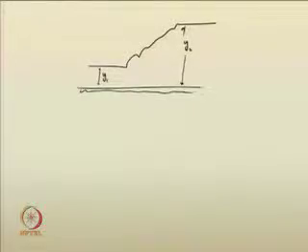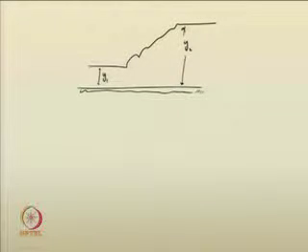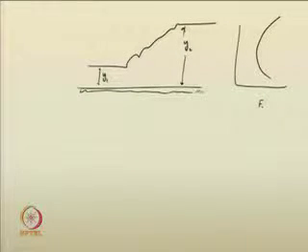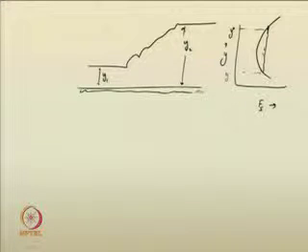Also for rectangular channels, in our previous analysis, we have approximated the bed channel to be almost horizontal. So, when you are dealing with such steep and mild cases, although the channel slopes are approximated to be nearly horizontal, based on the condition of flow, we suggested that it could be a steep channel or a mild channel. If you have seen the specific force, it may consist of a curve like this, specific force versus depth, and for the same specific force you have the corresponding sequent depth of the previous depth in the upstream.